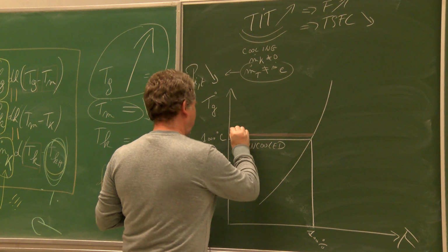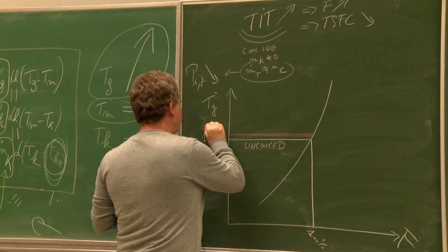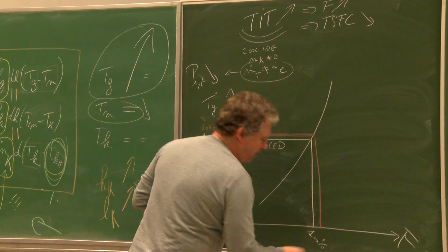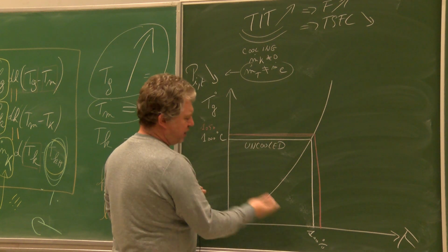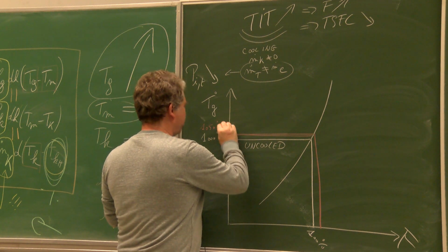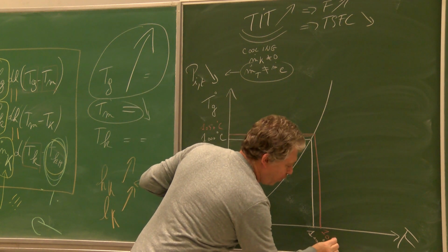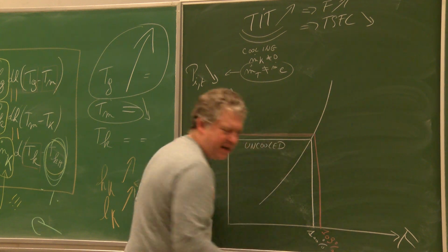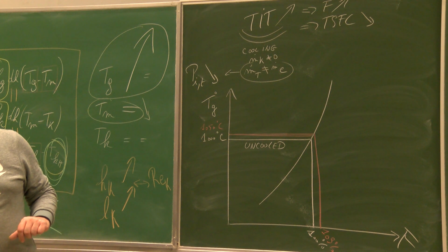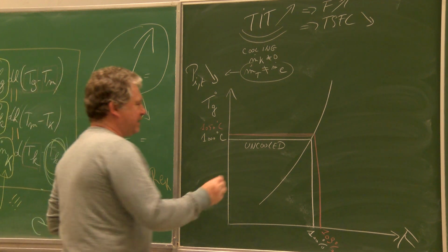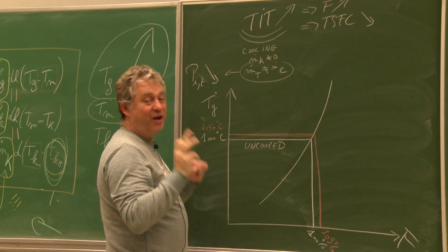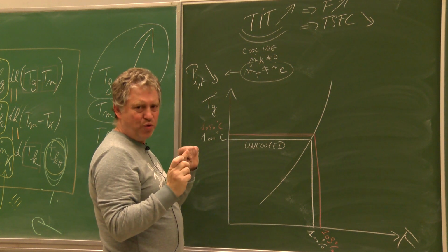With the material, you will not go to 1000, you will go to 1050, and instead of 1000 delivering 100%, with 150 degrees Celsius more, you will reach, I don't know, 103%, for example. Or you can use a totally different technology that is enabling a larger increase of the TIT, thanks to cooling.